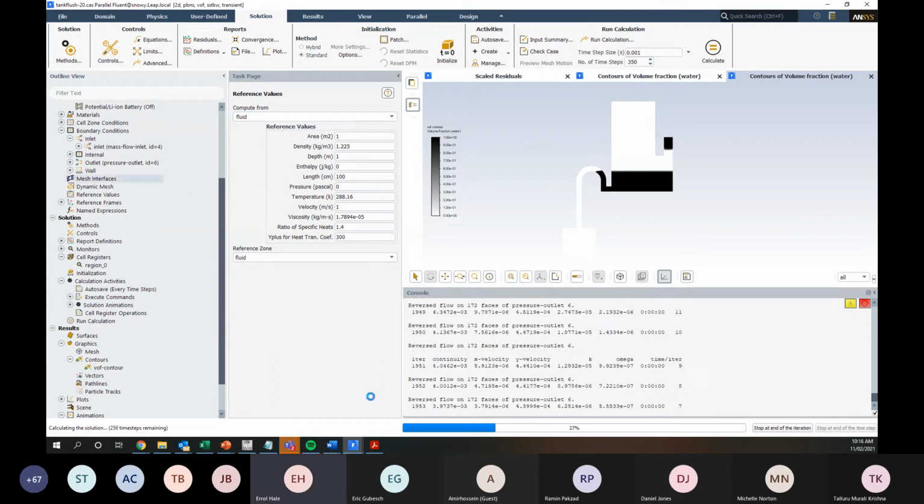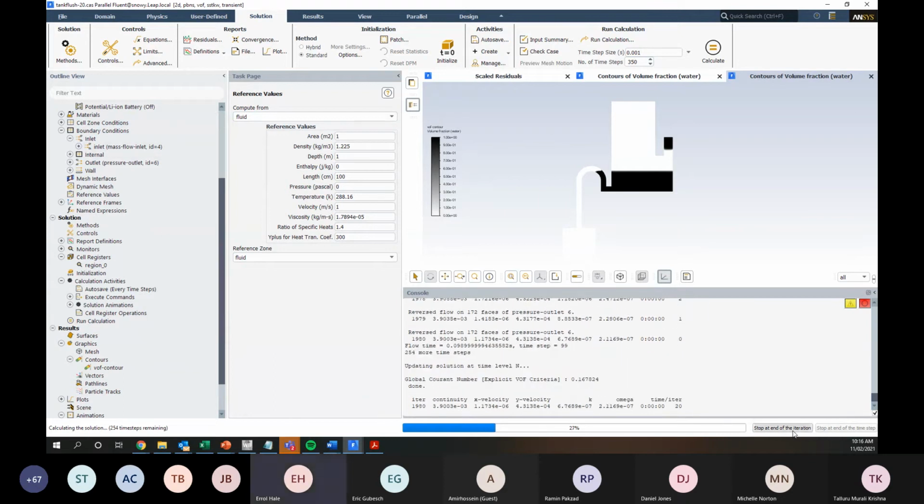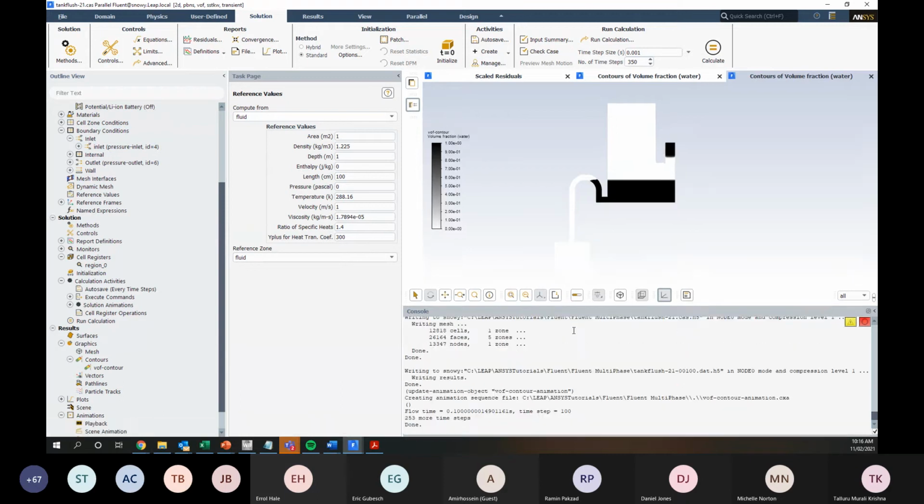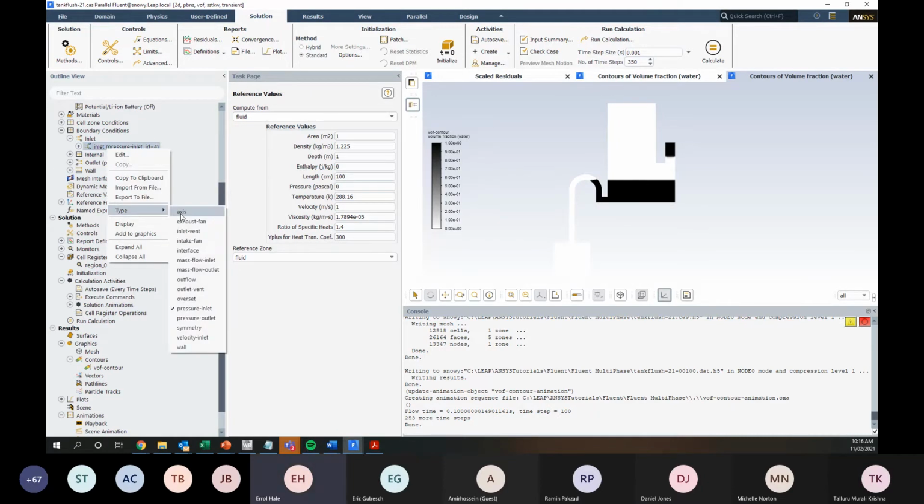In terms of the mass flow inlet, yeah. There's a bunch of different inlets that we can have. So we can have velocity inlet, pressure inlet, and mass flow inlet. There's also pressure far field, which can be useful for big 3D applications. And that's useful for more hypersonics, but there's not really much to a mass flow inlet.